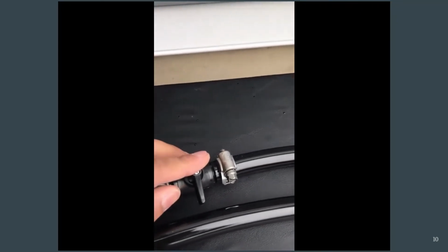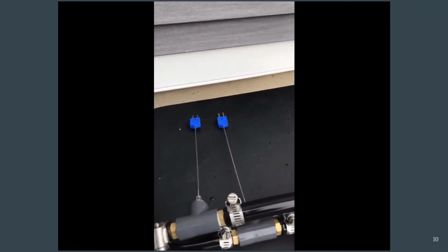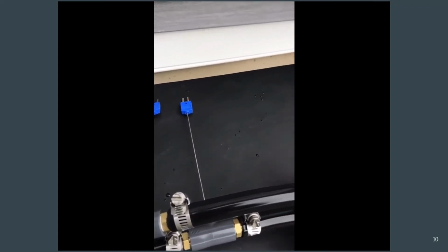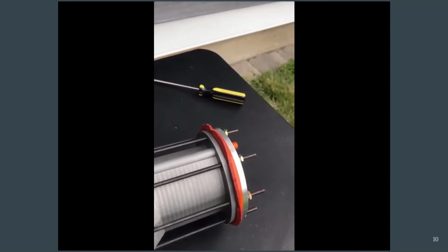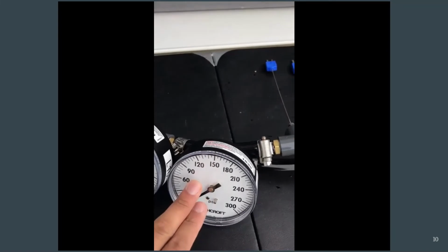So that'll flow into this loop through this control valve. Once it's opened, it'll hit this pressure gauge. It will then go through this thermocouple setup that we have here. The thermocouples are not connected as the heat transfer data is not important at this time. It will then flow through this top portion of the heat exchanger. It will spiral around. It will come out this second loop here. It will continue to flow through the other pressure gauge. We'll have an output pressure right back into our water containment.